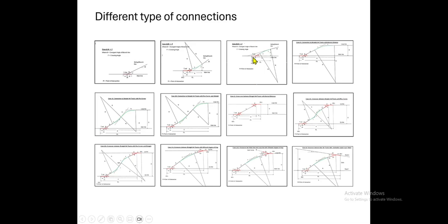Then the other situation, the divergent track, where the siding line is coming but the angle of inclination is less than the angle of crossing. Here our crossing angle is 4 degrees something, so if it is 2 degrees, the curve will be in a different way. So we have to introduce this connecting curve here, and for that, how do we fix the coordinates? This point is the overall length plus the y distance. This is one type of connection situation that will come.